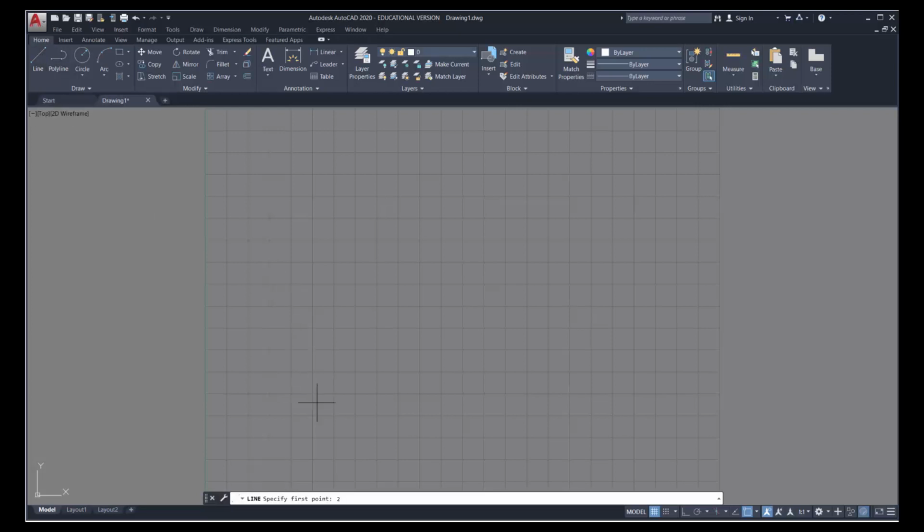That's an absolute value. Now remember when we first started this, we had all these different symbols that were on our screen. We're going to bring that back up. So press F12. And by switching to F12, what we've now done is switch to the relative coordinate positioning. So last time we typed in 2, 6 to get the second point. This time we're going to type in the relative position, or 4 straight up along the y-axis. So we're going to type in 0, 4.